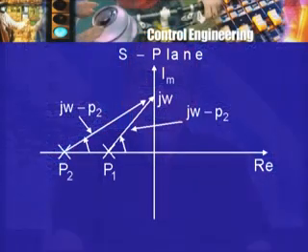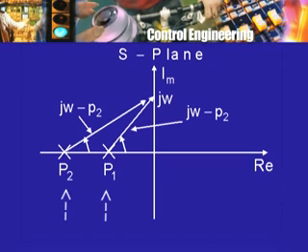So, for that, let us look at the simple situation corresponding to our feedback control system with proportional feedback. We have two poles here, a result of the two time constants, the electrical time constant and the mechanical time constant associated with the motor and the load. So, we have two poles, no zero, and we want to look at GH(jω).